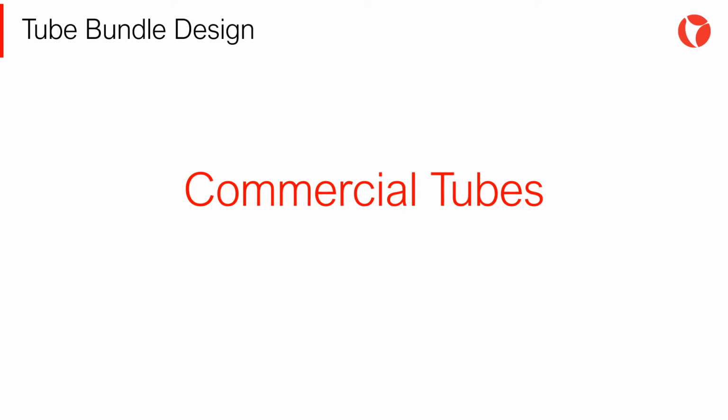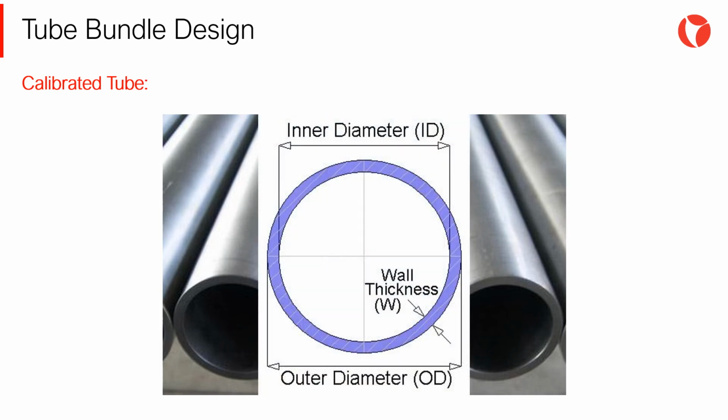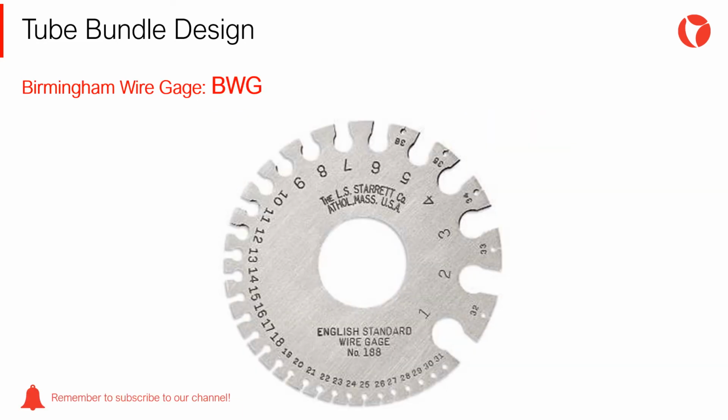Commercial tubes used for heat exchangers are different from pipes used for fluids transportation. The tubes used in the fabrication of shell and tube heat exchangers are calibrated. They are specified according to their outer diameter, which coincides with the nominal diameter, and the wall thickness. The wall thickness, or gauge, is determined according to the BWG scale from 1 to 31, where each number corresponds to a specific thickness.